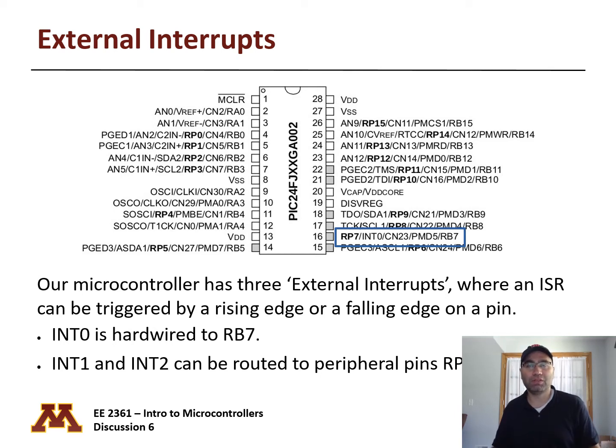So if this is enough for you, then that's good. If not, if you need a couple of other pins to be used as an external interrupt, then using PPS you can use any of these pins as a source of external interrupt. Okay, so very neat stuff.